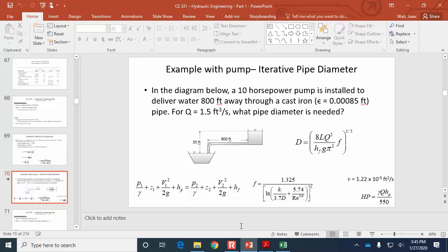By closing the valve, you're just introducing a little bit more head loss. This time, instead of due to pipe friction, it's a local loss. But that 6-inch pipe isn't going to achieve 1.5 CFS unless the pipe length is shorter or the lift distance is less or if it was smoother.